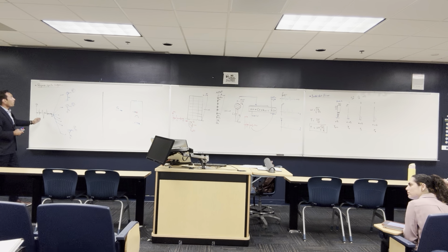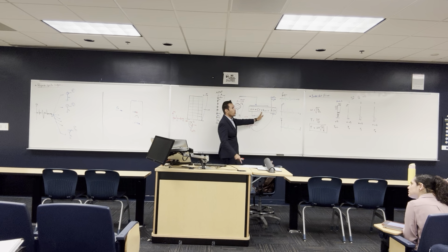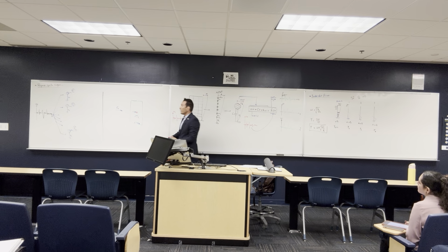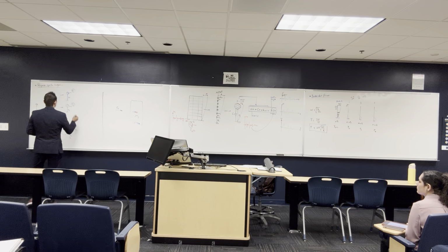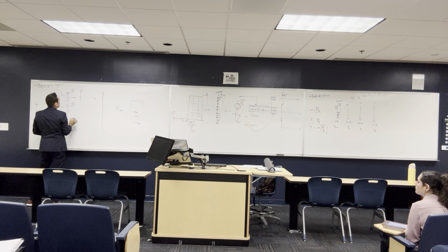Once you apply this, they solve the differential equation for each one of them. They put in the mass and the stiffness and the damping and everything, and they get the maximum acceleration for each one and the maximum u for each one. So they made something like this: after they solve, T and A, where A is u double dot.